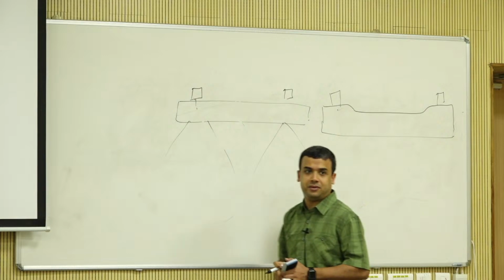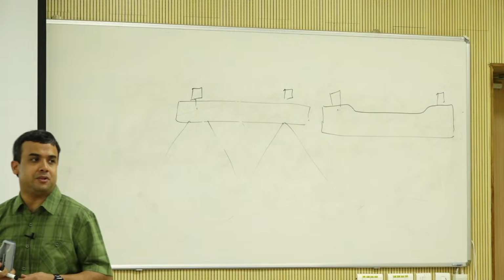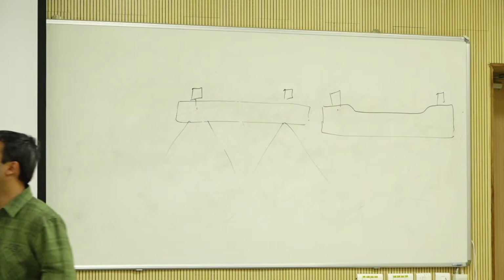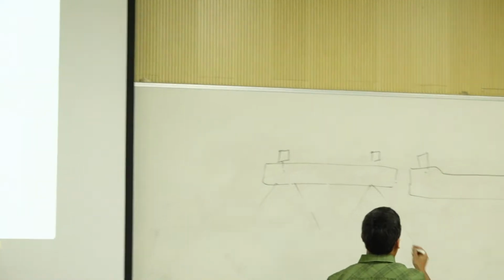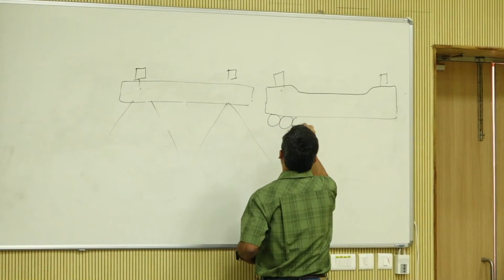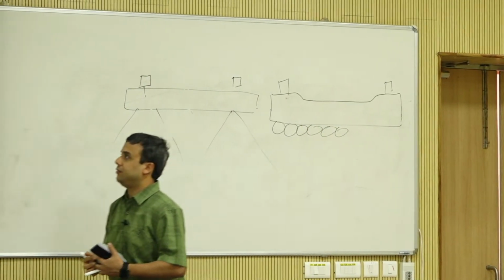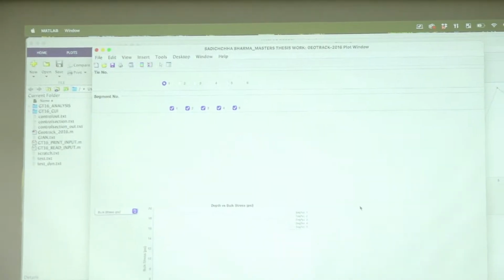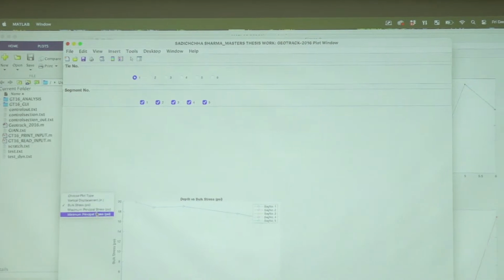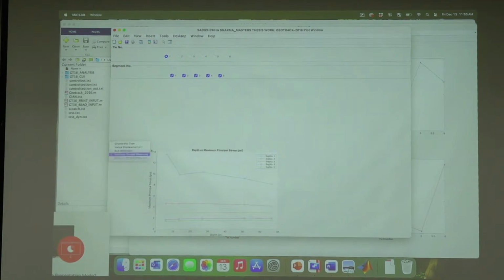That's how ties are designed basically, because the middle thickness, you don't need it. It's thinner. There is no load transmission happening. It's a beam, right? Save material. So that's what's happening here. The bulk stresses are also higher because segment number 1 is actually here. And then you divide that into segments, and 5 is kind of in the middle. So that's bulk stress. You can do maximum principal stresses, you can do minimum principal stresses, and all of that.